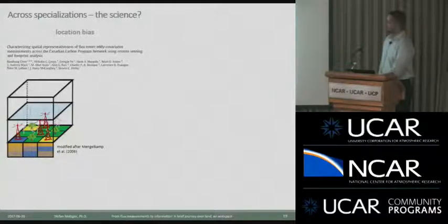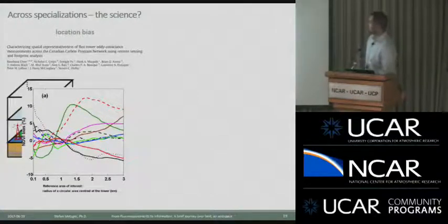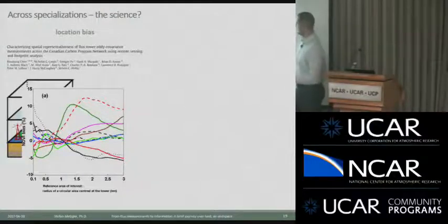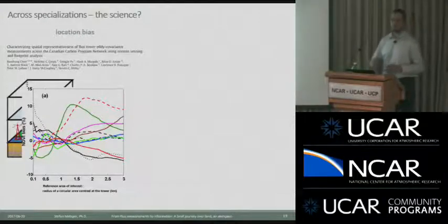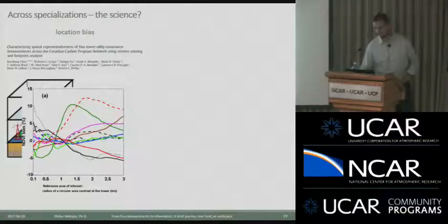of numerical models. This here is a study by Chen et al. What they show is essentially, if we have a tower measurement and we increase our area of interest relative to what the tower is actually measuring, we get a location bias. If you have a MODIS pixel, 1 kilometer square, and you want to compare remote sensing parameterized flux to your observation, you might easily be in the order of 10 or several 10% bias just by making that assumption.